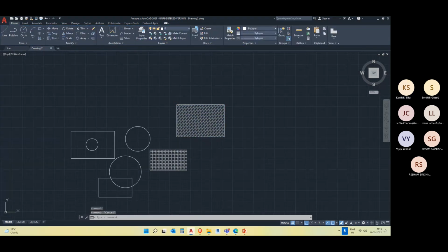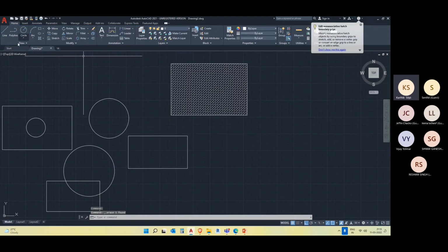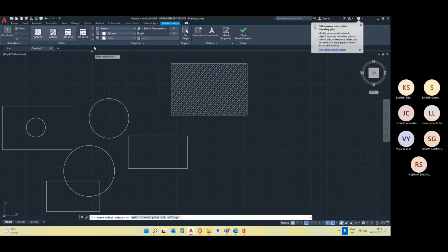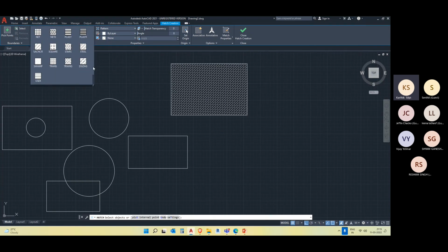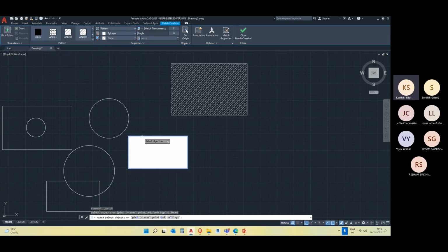Like let's say I just want to draw one more hatch. I'll go to hatch. So here are our different types of hatches. There are many varieties over here. So let's say I'm going to apply this particular type of hatch. Click on the surface, and you'll have it here. For this given 0.025, it's not visible. So let's say I'll make it 5. Now you can see that is visible. Or let's say I'll apply 50. 50 is not appropriate for this given hatch, so I'll go back to 10. So these things you have to manually adjust. There is no other option.